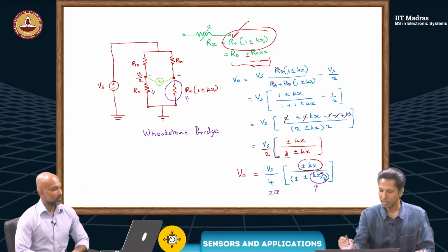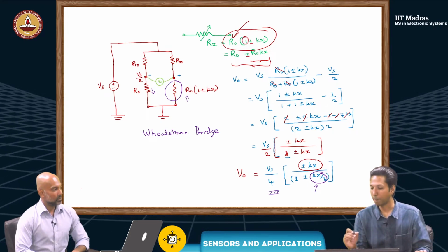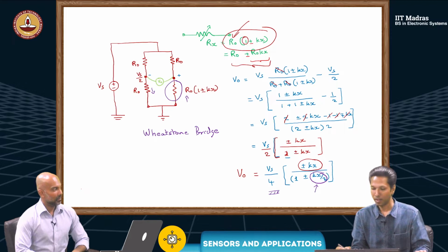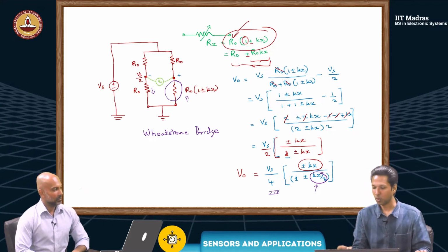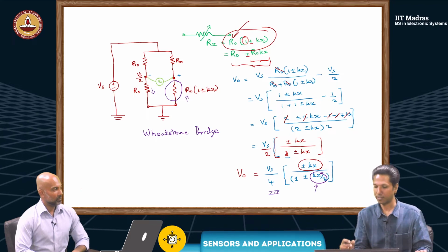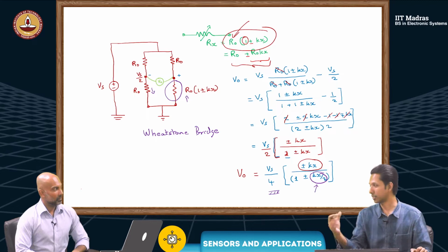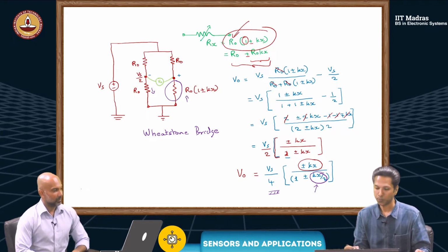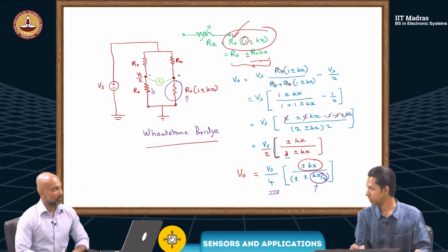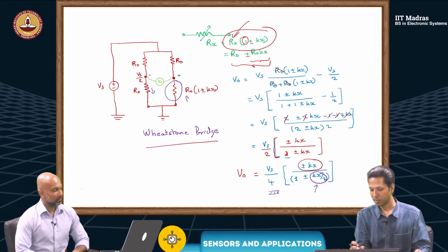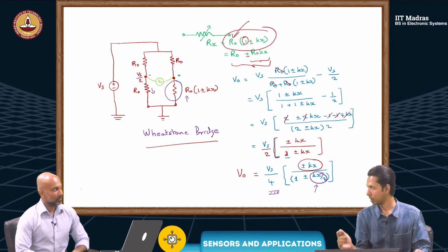One thing we realized is that the equation is like 1 plus Kx, or minus Kx, and the Kx quantity may be very small. So, how do you measure that Kx when the 1, which is probably very large compared to Kx, is present there? Correct. So, then we brought in the Wheatstone bridge, which somehow looks at the difference alone and gives an